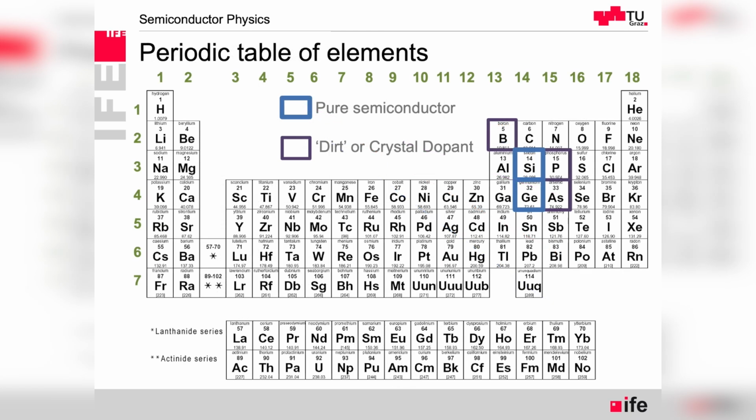Now, if we would like to add doping, in particular I will talk about germanium and silicon, because these are simple, one-element crystals, not like gallium arsenide, a compound semiconductor. If we want to add doping, we will be considering either the column on the left-hand side with one less valence electron, or the one on the right-hand side with one more valence electron.